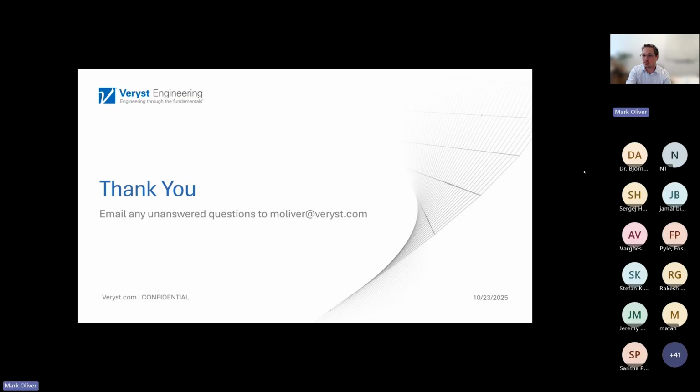You do that first because that's something you can get quickly. And if it's important to have at least some data to go on in analyzing the creep in the structure, then that gets you started. And then when you do that, you also kick off a series of creep tests that run over weeks or months. As that data comes in, you can compare it back to your TTS and verify that the creep curve we collected with TTS is conservative, and the creep isn't going to be as high as what we've been predicting.